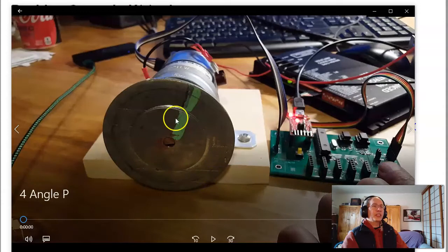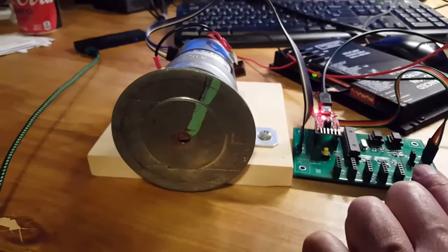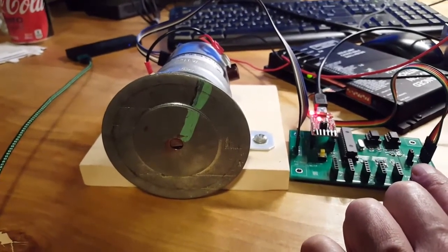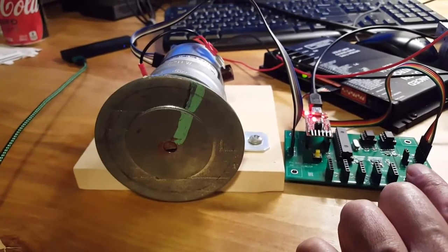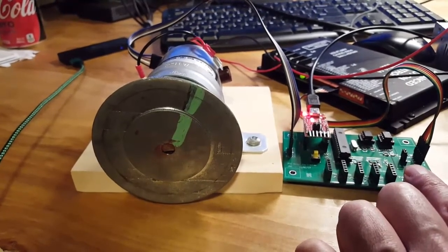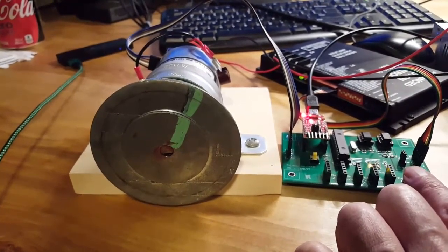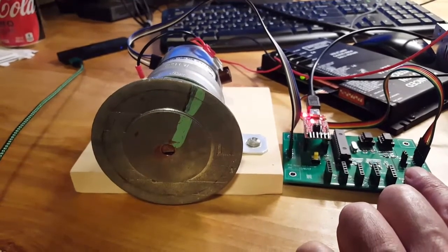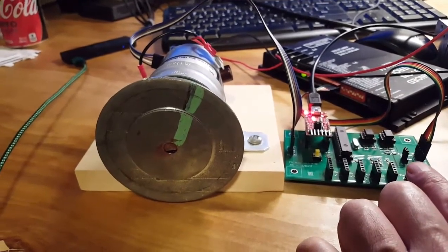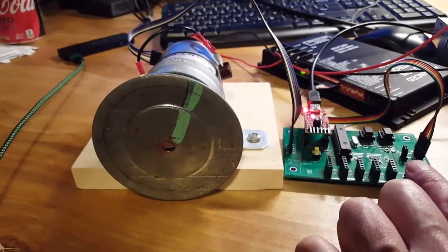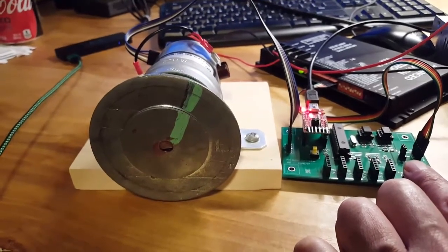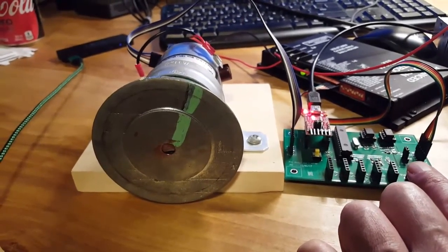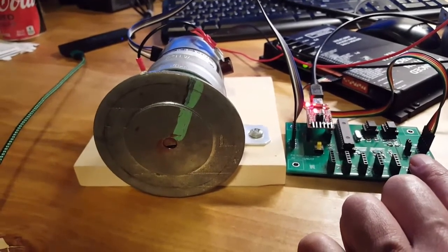In practice, it's a little bit different, because motors are nonlinear. I've got more friction at low speeds. In fact, when it's stopped, I have static friction. Here we have digital position control. I've got a proportional feedback, trying to control it between 0 and 5 radians per second. When I put it at the breakaway point, there's just not enough gain to get it to move. In theory, this is a type 1 system, should be no error for step input. In practice, the static friction is too large.